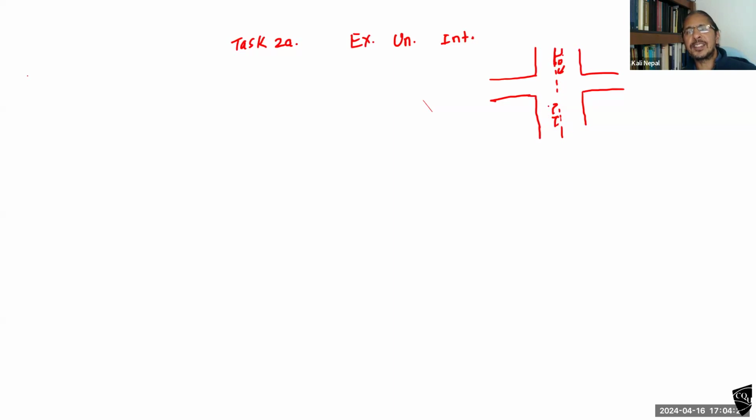For all others, through and left share the same lane. From east-west, currently only one lane for left, through and right, the same from the west, only one lane for all 3 movements. This is the first analysis you need to do.